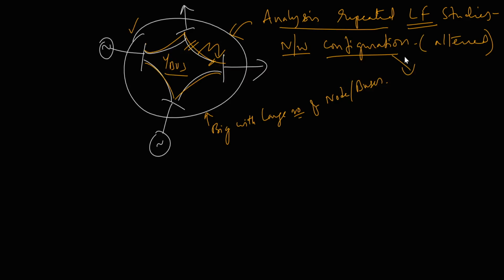He needs to form the Y bus to conduct the load flow study, and from it he wants to see the bus voltages, the new line flows, and the power losses in the network. He carries out these analyses assuming there is a fault in this line and he has removed it, and now he is visualizing the network behavior.